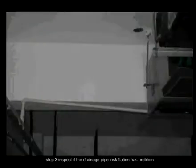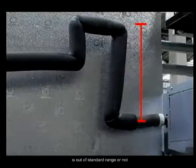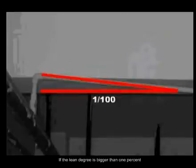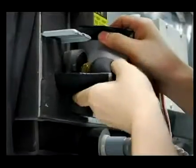Step 3. Inspect if the drainage pipe installation has a problem. Check if the level and slope of the condensing water pipe are out of the standard range or not. If the draining pipe is jammed, the condensing water cannot be discharged. Check if the lean degree is bigger than 1%, and if the pipe connector and throttle part are well heat insulated.